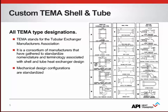Now you can see from the figure on your screen that each TEMA heat exchanger style has a 3-letter acronym to designate the front head, shell, and rear head design types. For the front head, types A, B, and N are the most common. Type A is a removable channel with a removable cover so that tubes can be accessed for inspection and cleaning without disconnecting process piping. Type B is a removable channel without the removable cover, for a less expensive option with similar features to the Type A.